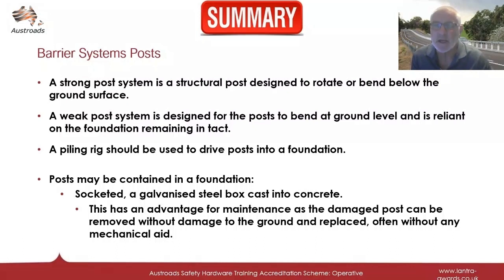Posts may be contained in a foundation. It's socketed, a galvanised steel box cast into concrete. This has an advantage for maintenance, as a damaged post can be removed without damage to the ground and replaced, often without any mechanical aid.